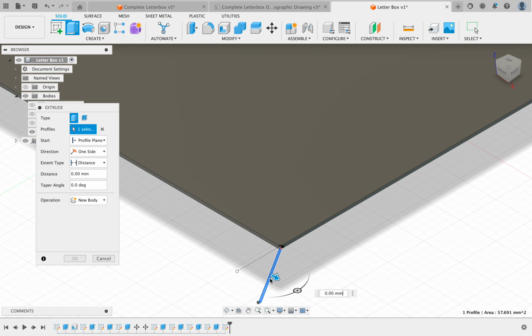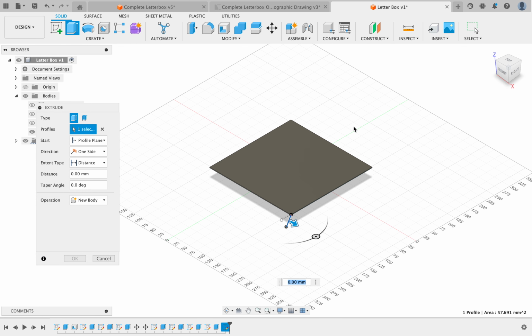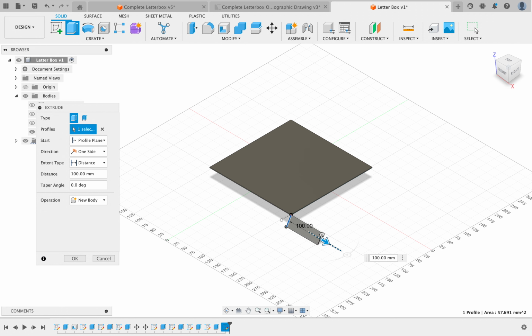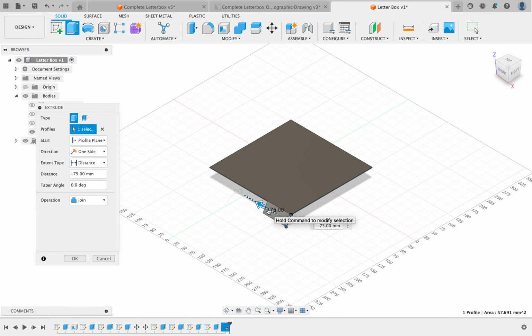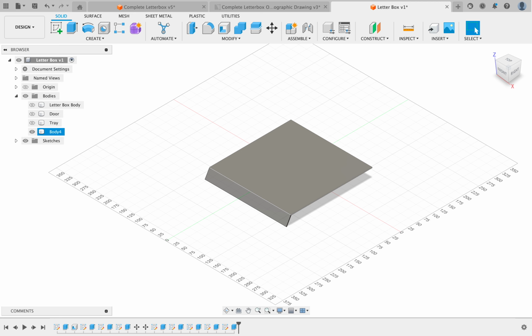So I'm going to select that, and because of where it's sitting on the grid, on the plane, you can see there that it actually wants to come out this way, but from where it's sitting, it actually needs to minus on that x-axis. So we're going to go minus 260. Right. So now we've got our lid.